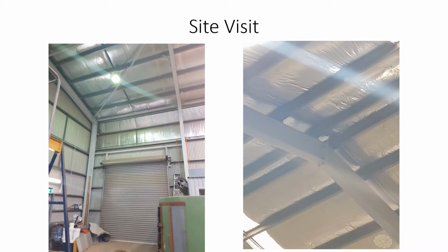Here are photos inside of the structure, showing the columns, rafters, bracing, and side rails. In these photos can be seen columns. These are vertical structural members that transfer loads from the roof to the foundation through compression. Beams are horizontal structural members which carry transverse loads. These are loads applied perpendicular to the longitudinal axis of the member and cause bending and deflection. Rafters are beam members that support the roof system.